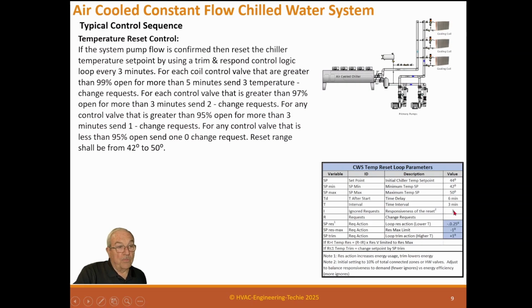Now, they recommend you change this number be set to 10% of your total connected valves. So I'm saying I've got 30 valves, so this is going to be 3. And they said that they've tested this, and this guideline 36 recommends that 10%. So here it is right here.